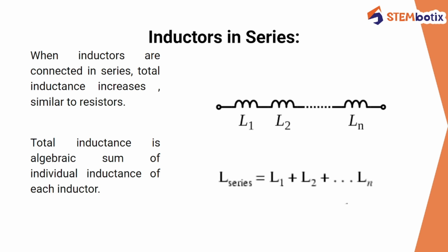First we will see n number of inductors connected in series. Here in the image, you can see that from L1 to Ln, the inductors are connected in series because they are sharing only one common node. L1's ending point is connected to L2's starting terminal. Similarly, Ln-1's ending terminal is connected to Ln's first terminal. Hence it is a series connection.